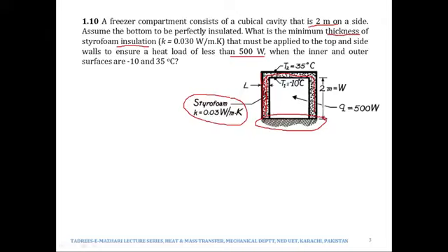So the heat that will be transferred from the surrounding air to the sheet metal panel or to the outer surface of the refrigerator would be the same as the amount of heat that will be transferred from that sheet metal panel or that plastic body to the insulation, and the same heat will flow through the insulation, and the same heat will then flow into the freezer or refrigerator if the system is under a steady state.